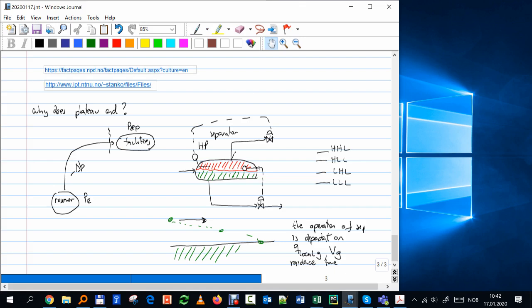and then everything else will change. Yes? How do you define velocity of gas here? Like what cross-section area do we consider? Because it should be constant, then you use the nominal. Okay, so if you see the tank, this will be the area of the gas. Then the velocity of the gas will be the Q of gas at that particular pressure and temperature divided by the cross-section area, which simply will be the area divided by 2. The area for gas will be constant. You assume that it will be constant. So if you increase pressure or decrease pressure, this rate will become bigger or smaller.